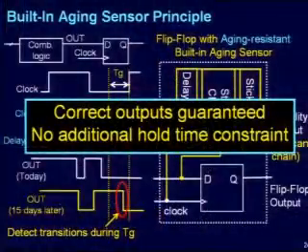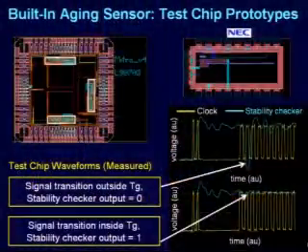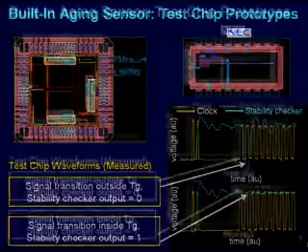The other thing that people worry about a lot with these kinds of techniques is whether it imposes any additional hold time constraints in your design. There has been some work that imposes hold times, and hold times are not good. No one wants hold time issues because that can completely mess up your design. But techniques like this never impose any hold times. So, do these things work in real life? I was pretty high level about the details, but yes, these things do work in real life. There are actual test chips which show that these things are operational and they do the right thing.